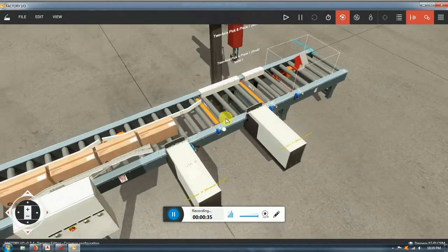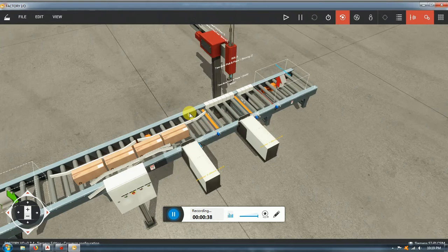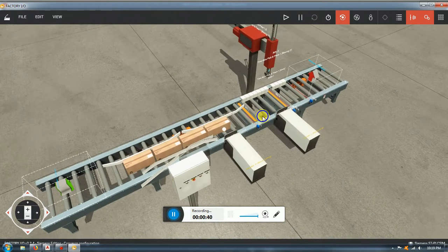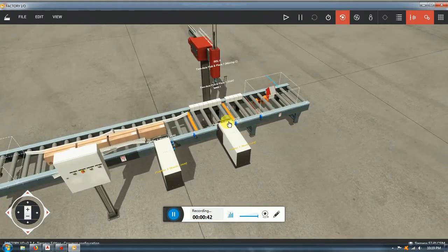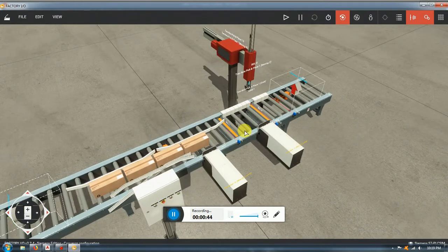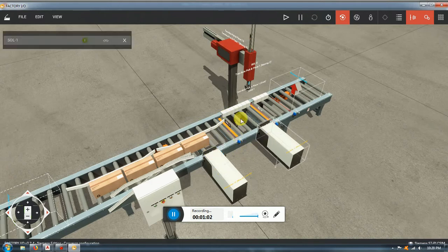Okay. So remember the machine is going to be quite simple, and it is actually gonna be pretty much quite pneumatic. Yes, there are gonna be motors for the conveyors, right? There's gonna be electrical stuff like the photo eyes, diffusion sensors, but the main things, the clamps, the stops, that's solenoid 1 or 2, and the main stamper, they're gonna be pneumatic.